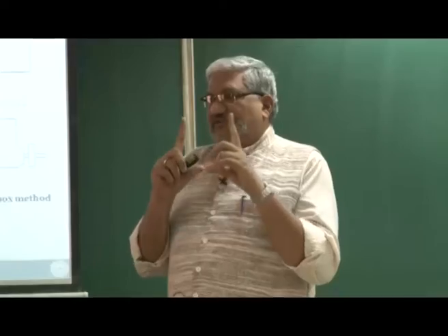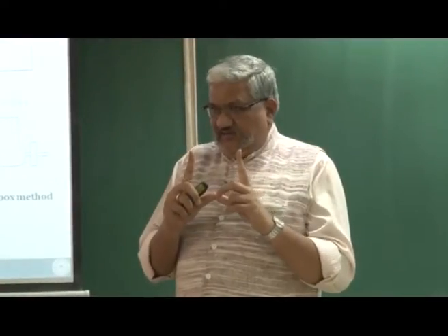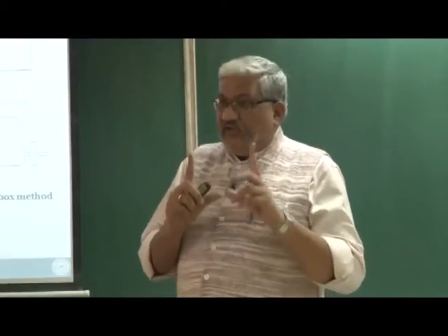If there is one single cylinder 1 liter engine versus a 1 liter 4 cylinder engine, which will have higher air pulsations? The single cylinder engine or the 4 cylinder engine? In this case it is 1 liter 1 cylinder, in this case it is 250 ml times 4 cylinders. The total swept volume is the same. The single cylinder will give you large pulsations.